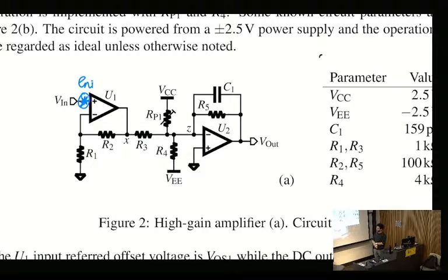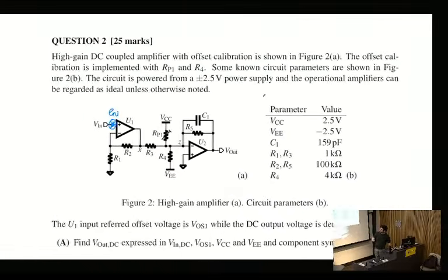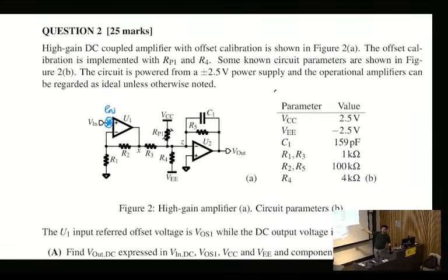So I guess the takeaway from this is just the logical steps of, okay, here's the problem, here's what's causing it. The problem being that we're using it as a reference voltage, and so the only way to fix that is with a diode. Or there are other ways to fix it as well.